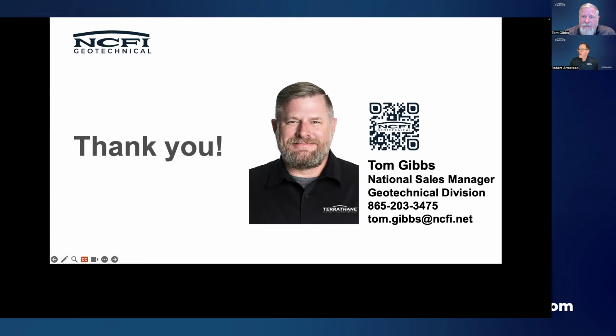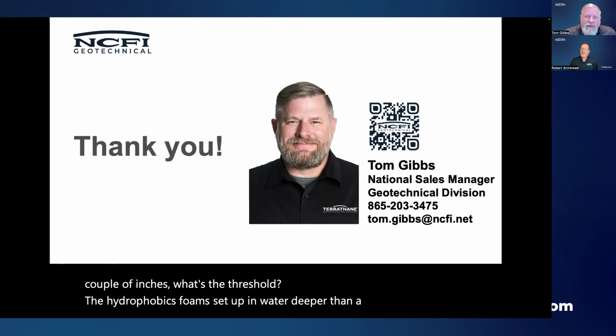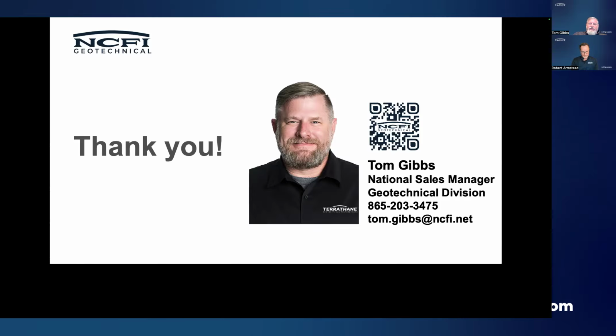Wonderful. With the hydrophobic foam, can it set up in water deeper than a couple of inches? What's the threshold? Can it be injected in water? Yeah, you could have a cavity or a void that's completely full of water. It's still going to make good foam and displace the water and push it out of the way. That's why we put it in there, because we do have a couple of systems that are not hydrophobic. One of our most popular concrete lifting systems, our 2.8F, been around for years, one of our oldest systems, is not hydrophobic.